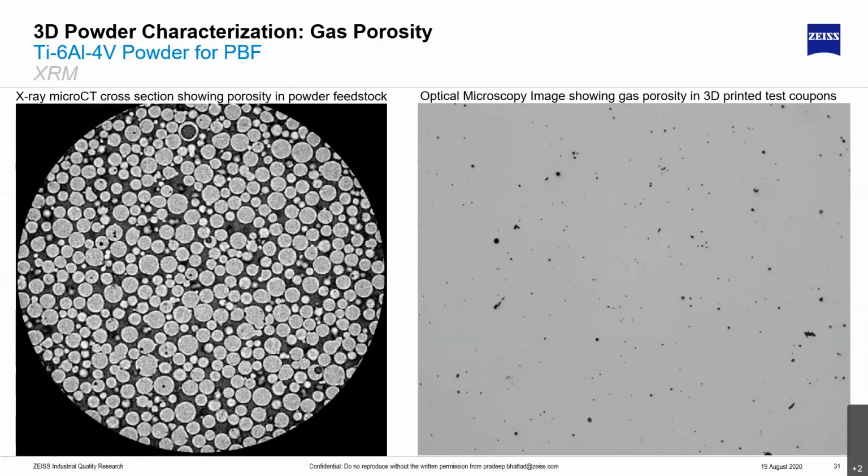And like I said, a single tool will not be able to give you all the answers, but the idea is if we have a particular defect and you cannot trace the source of it, then you might need to do some level of investigation. And if the source of porosity, crack or part failure is critical enough, then for every incoming batch of powder, you might also start nipping the problem in the bud, is what I'm trying to say.